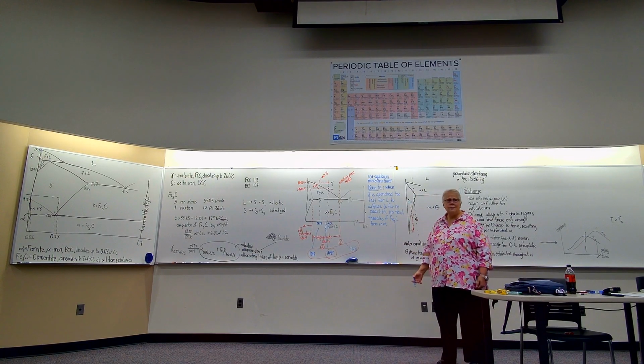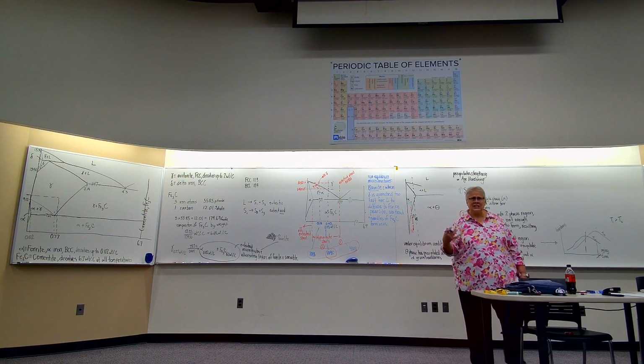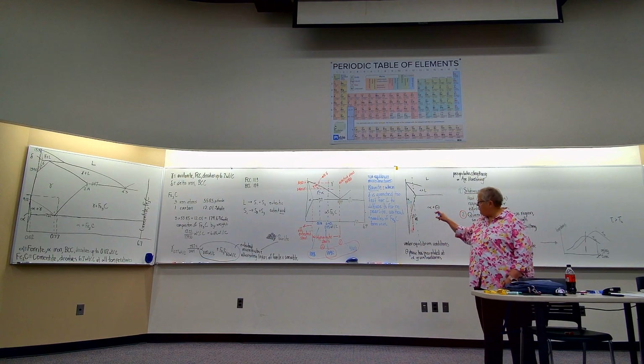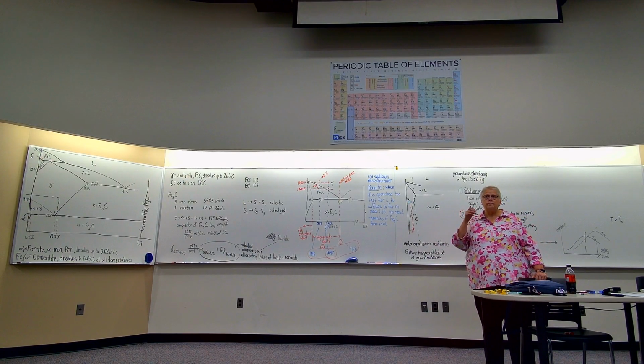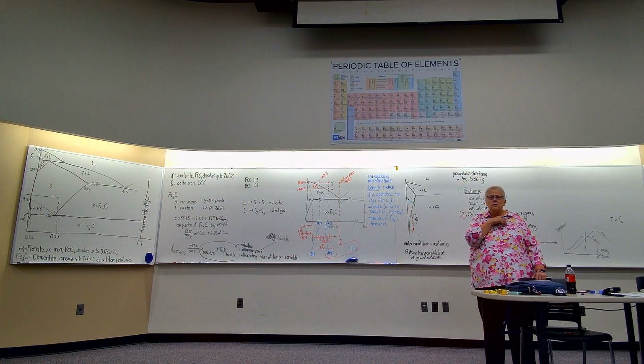Now they're tiny, so it's a much smaller distribution of that hard phase, and so bainite is harder and stronger than pearlite because of that.